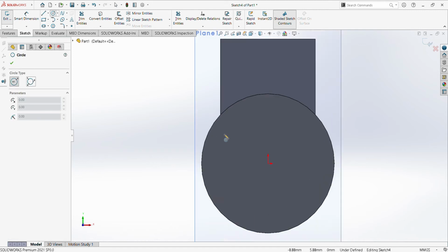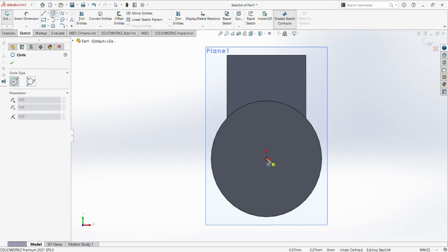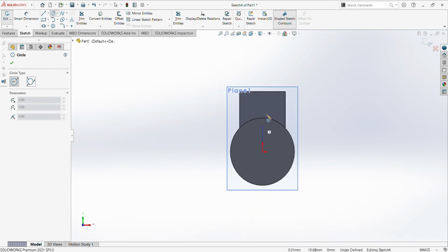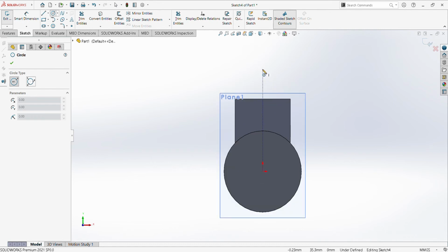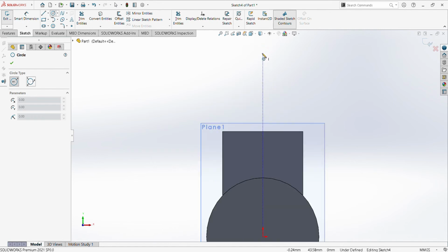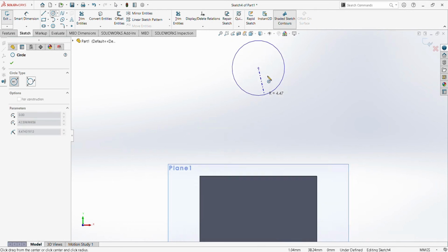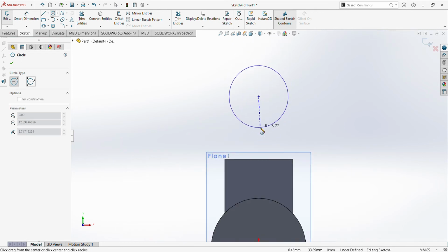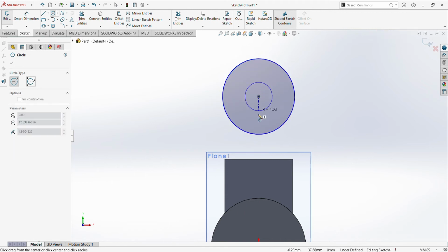And then selecting circle command, then from this point or origin, we will have it as a reference. We will drag it all the way up, then have 2 circles to that point, then change its dimension using again Smart Dimension.